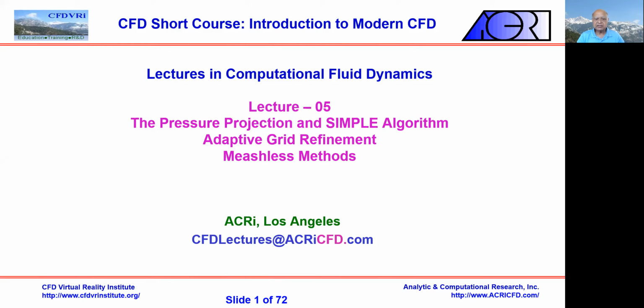So today's lecture concerns the pressure projection and the SIMPLE algorithm. And I will add to that the adaptive grid refinement and the meshless methods, which are becoming very popular and are very useful in modern practice.